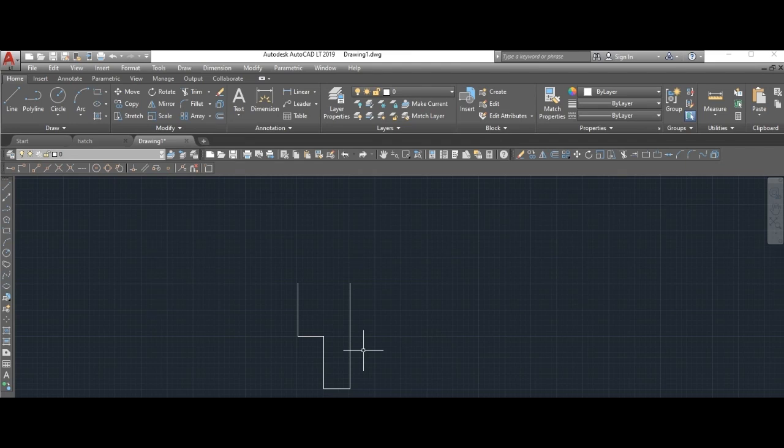Now the next thing I want to do, I'll still pick the line tool. I click the line tool here. I click from here. I can extend it to this position, but I decide to leave it at the midpoint, and you will see the reason why. Click here, I press enter. I come to this other position, click line again. I click this position, I bring it to the midpoint here. I click and I press enter. So I have two lines here.